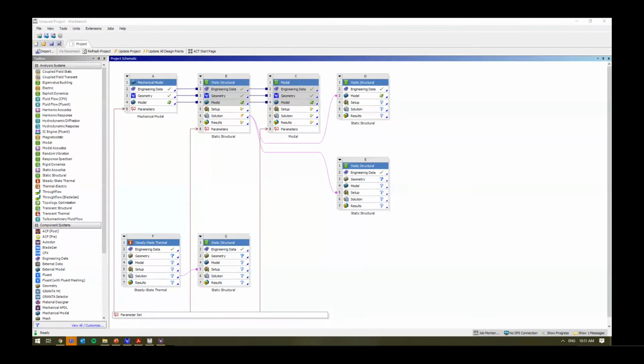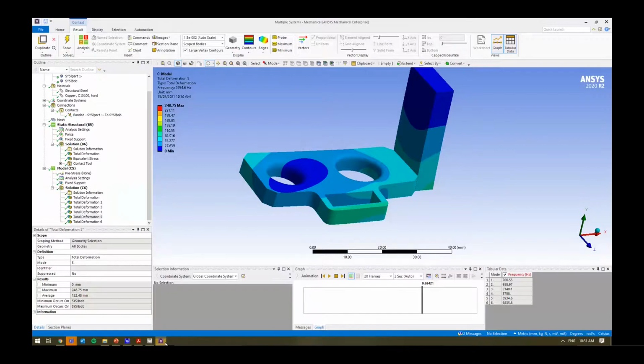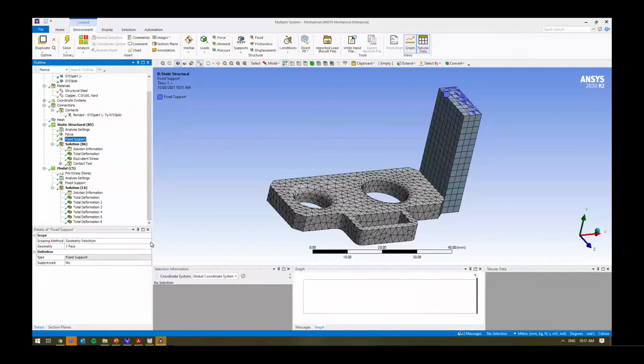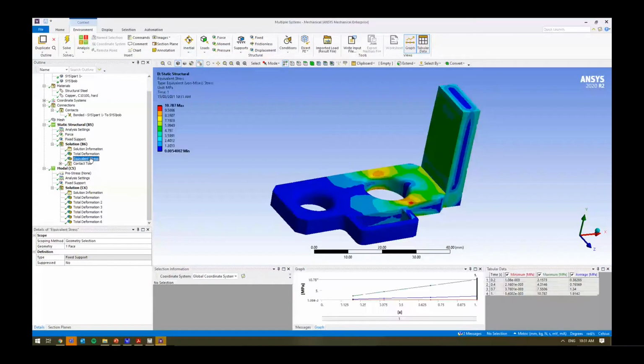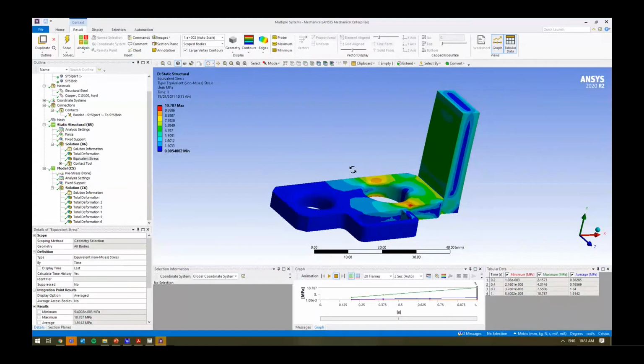So Stefan, because the materials are not able to deform, does that lead to non-accurate high stresses at the face? Yes, so that's one of the things we'll talk about tomorrow. He was just saying, because we've got a fixed support there, we're fixing all degrees of freedom. We can start to get high stresses around some of these areas.